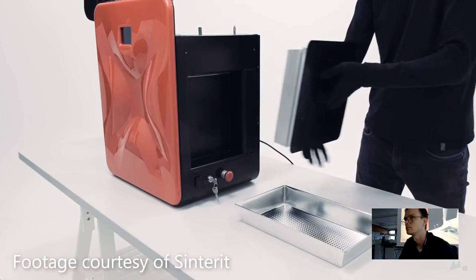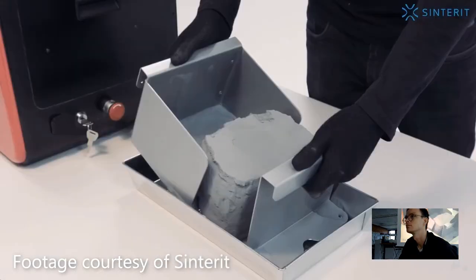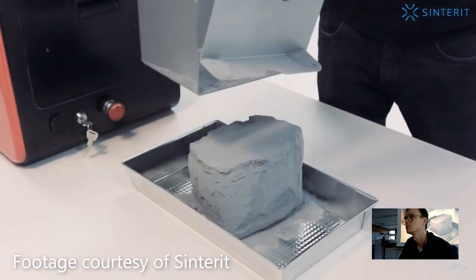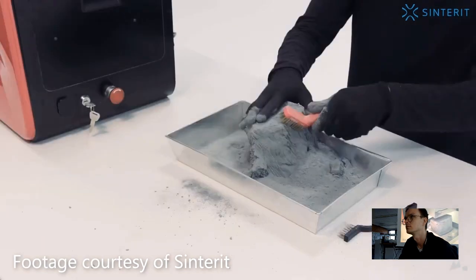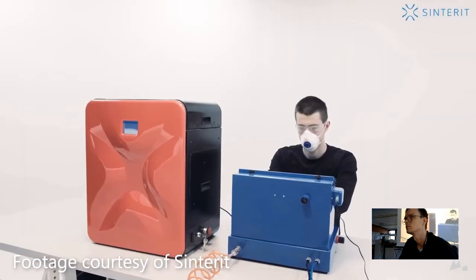And let's go to our last point, the post-processing. So as you can imagine, you have all this loose powder and you have to pull these parts out of the loose powder. Yes, it is as messy as you can imagine. In the videos, you can see how they pull it out and dust it off and use an air blower to clean it off, and then they use a sandblaster to make the parts look fantastic. In an industrial circumstance, it's fine. You can deal with that powder. In a home environment like where I am here, no chance. It's going to be extremely messy.